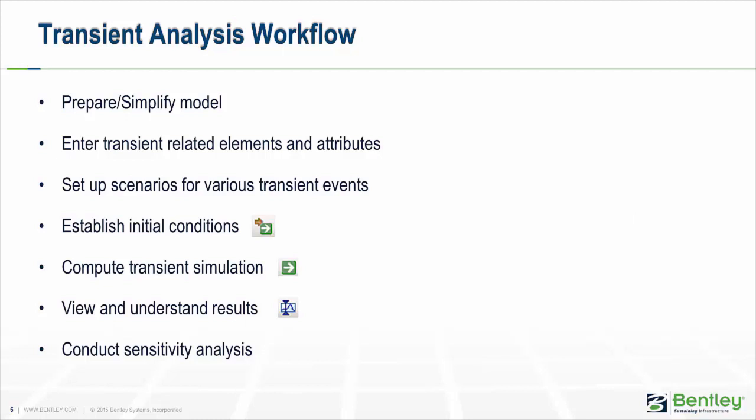Lots of tools for viewing and understanding the results, and that's a key area that we're going to touch on. Make sure you're nice and efficient with understanding those results. Last thing you usually want to do is a sensitivity analysis, where if you're not quite sure about a certain setting of something, or if you're not sure what size of a tank or size of an air valve you might want to use, you can basically vary those parameters and check the transient response to that to see if it has a significant impact on that, so if it's something that you need to really refine.